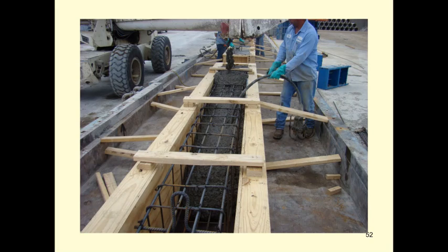And then you use this called the vibrator. This called the vibrator, okay, is used to make concrete compact. Okay, that means when you put the vibrator into the concrete, the vibrator will shake the concrete and make the air go out of the concrete, and the concrete will get more compact, less void per se.